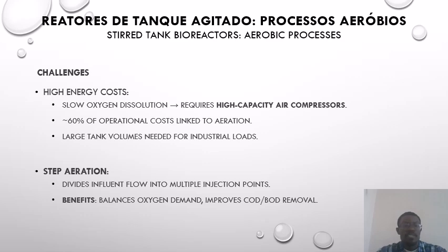What are the challenges to this process? It's actually challenging because of the high energy cost, because it requires high capacity air compressors to keep this process going. Approximately 60% of operational costs is linked to the aeration. Also, large tank volumes are needed for industrial loads. But the benefit of this is that it balances oxygen demand and improves BOD and COD removal, since it divides the influent into multiple injection points.